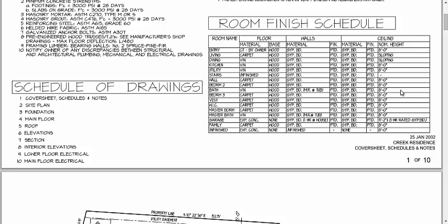So for an example, if I say, go hand me that 2x4. Well, you guys know what a 2x4 is. If you'd actually go pick it up and measure it, you'd find out that a 2x4 is only 1.5 inches thick by 3.5 inches wide. So we don't say, go pick me up that 1.5 inches by 3.5 board. Again, the name or the nominal dimensions is 2x4.